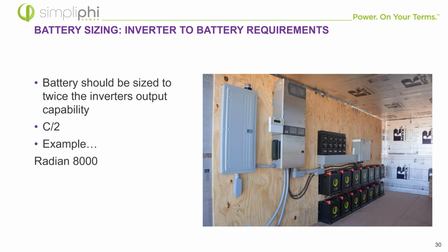This just adheres to that C/2 guideline. Oftentimes, inverters don't have the ability to limit the output. So if you stick within that C/2, you're going to make sure that there's no chance of ever damaging the battery. If you do need to go into those cases, like I have one battery and a 3,000 watt inverter, I definitely would recommend checking out my more advanced trainings posted on our website that go over some techniques to ensure that the battery is safe on that system.